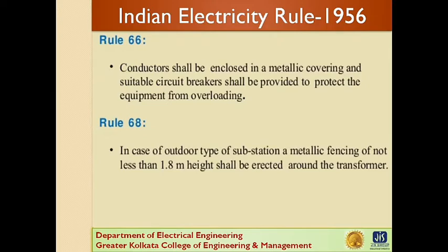Rule 66. Conductors shall be enclosed in a metallic covering and suitable circuit breakers shall be provided to protect the equipment from overloading. Rule 68. In case of outdoor type of substation, a metallic fencing of not less than 1.8 meter height shall be erected around the transformer.